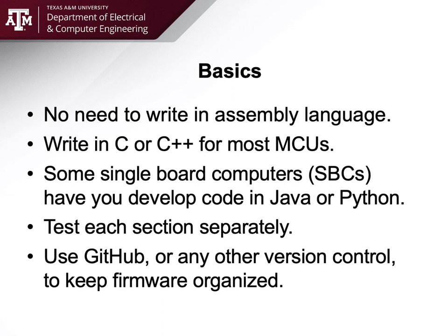Most of these processors operate at a high data rate, high MIPS, millions of instructions per second. They're way more than the speed you would ever need for your project. And the performance increase you'd get out of assembly language in code space and speed just isn't worth it, even if you were more efficient. So write all your code in C or C++ for most microcontrollers. I usually recommend C for most general embedded microcontrollers. It's kind of the default language.